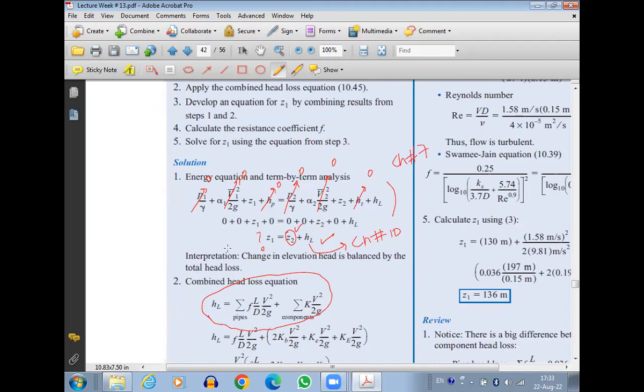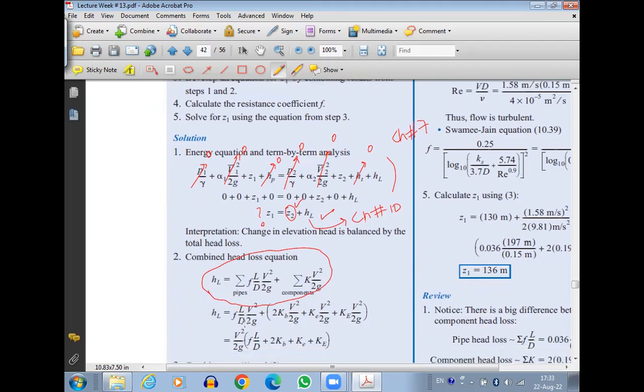So we have this formula, HL equals to. Now, what we can do is that we can remove the summation sign here because the rest of the things would remain the same. The only difference is the length; because we have three different lengths, we can add them together. So we'll have just one formula for the case of the pipe length, for the case of the major losses. For the case of the minor losses, we have now components.